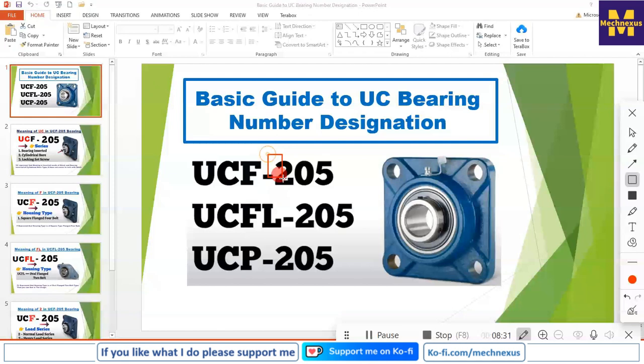And these two represent the load conditions. So here the number is 2, meaning it is designed for low load conditions. If it is 3, then it is for heavy load conditions. And the last two digits of a UC bearing, if we multiply by 5, then we get 25, which will be the bore size.